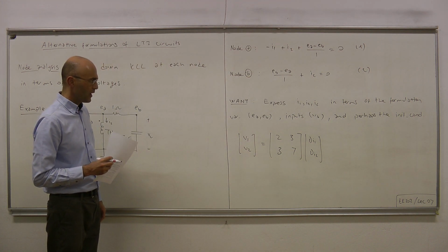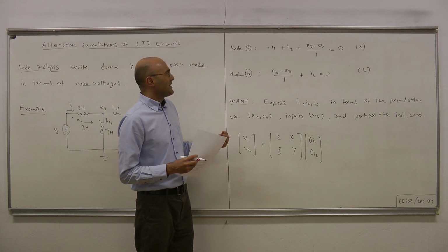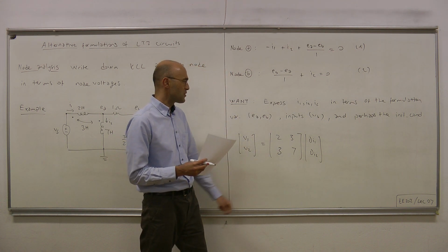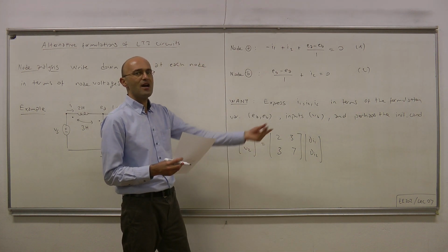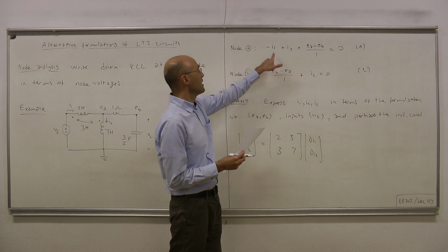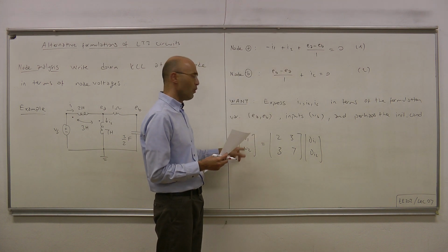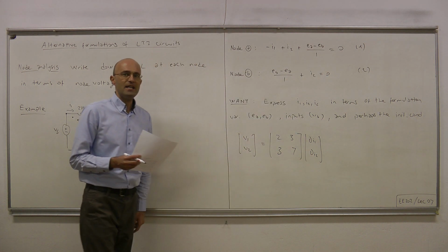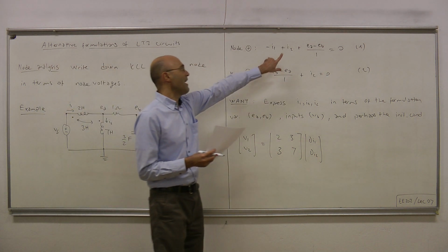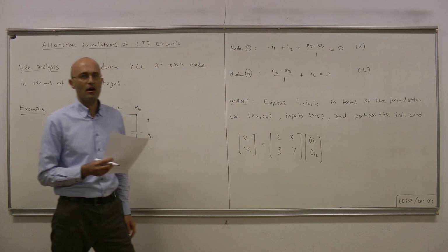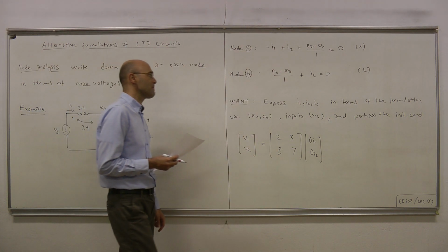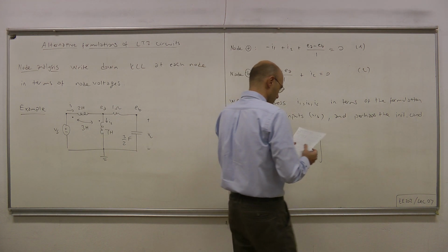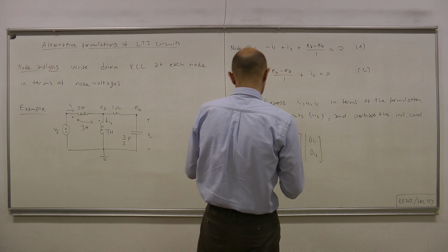Okay, now what we plan to do is, we first multiply both sides with the inverse of this matrix. So we will have di1, di2, and then by integrating those derivatives, we will obtain I1 and I2 in terms of the voltages. And then those voltages we will express hopefully in terms of EA, EB, and VS. And then we will have obtained I1 and I2 in terms of our formulation variables. And we will do a similar thing for the capacitor current. So let's do that.